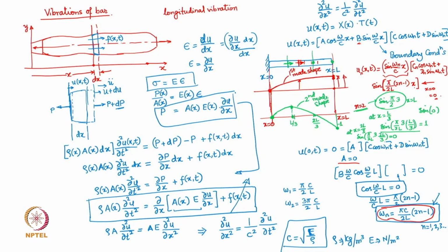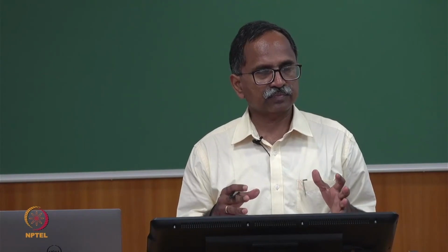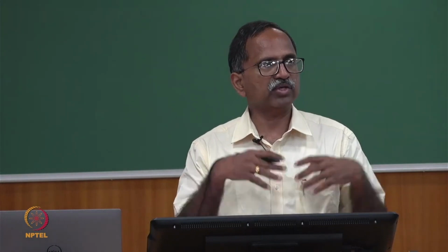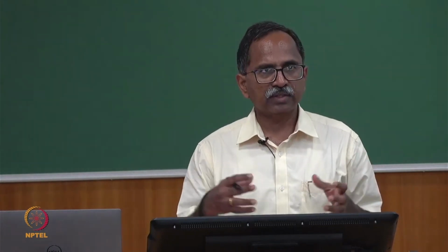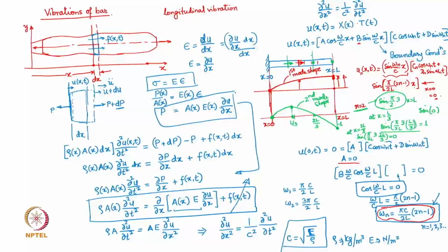Now what is the relevance of these? Knowing the mode shapes, in general I am saying that if I know that this bar is going to vibrate close to its second mode because of the operating conditions, then any mounting on this bar would be preferred to get located here.